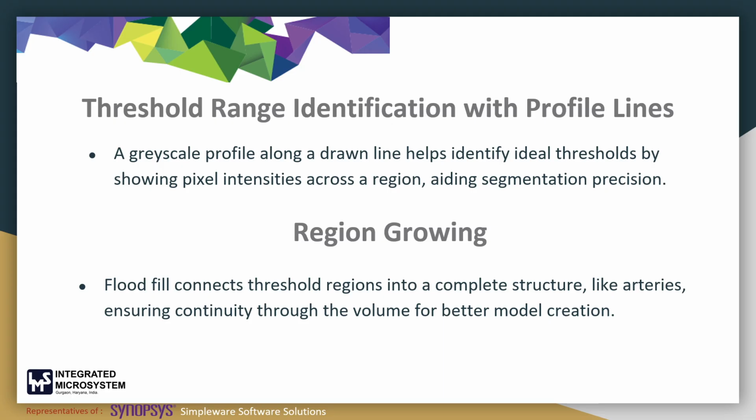These tools allow the user to draw a line across an image slice and view the grayscale intensity profile. It is particularly useful for refining segmentation thresholds by identifying where pixel values shift across tissue boundaries. This analysis helps tune segmentation thresholds, evaluate transition zones, for example blood-tissue interfaces, and detect partial volume effects and image artifacts.